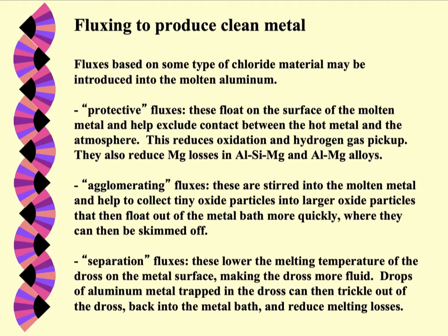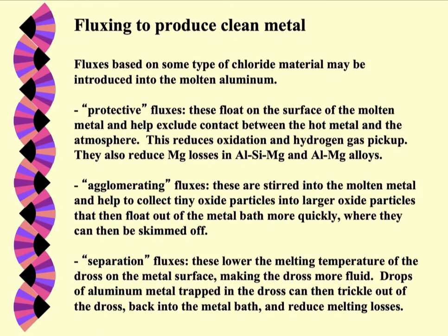If you're using alloys with magnesium, as it circulates, little atoms of magnesium come near the surface, form magnesium oxides, and then you lose it from the alloy. So in other words, they preferentially form an oxide on the surface, and then you'll lose that magnesium in the alloy, which is an important element.